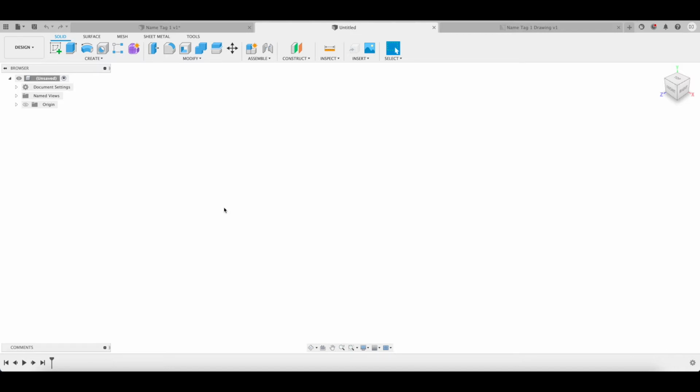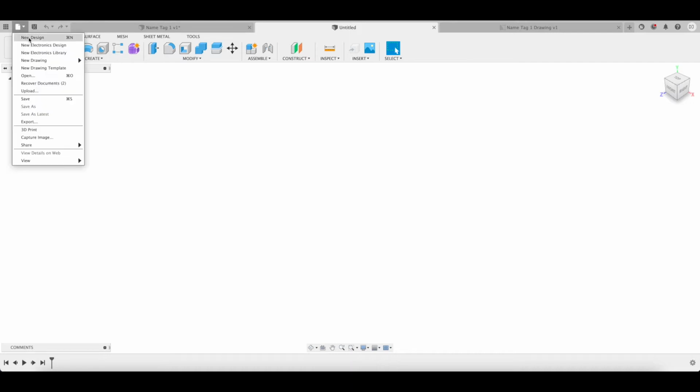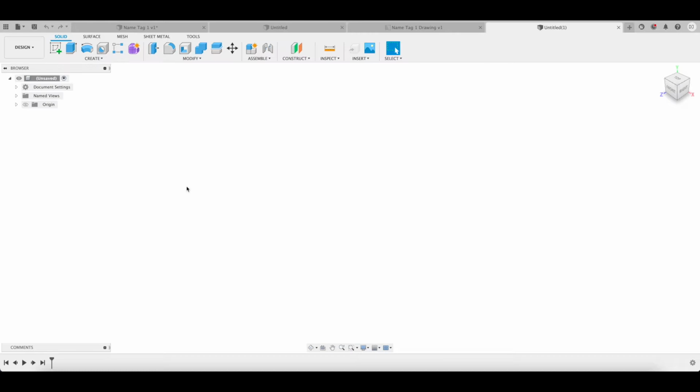Hey guys, so today you're going to learn how to make a basic name tag in Fusion 360. This is a great beginner project because you can learn about the different things that will get you started in CAD. So first thing you want to do, if you don't end up at this page, like it says untitled, it's a design, you're going to go to new design, which you can also say Control N to create the new design.